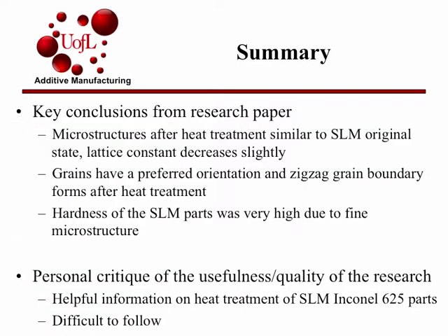The key conclusions from the research paper: the microstructures after the heat treatment are similar to the SLM original state. However, the lattice constant decreases slightly. The grains have a preferred orientation, and the zigzag grain boundary forms after the heat treatment. And the hardness of the SLM parts was very high due to the fine microstructure of the parts.